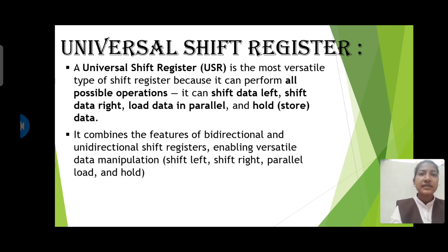Therefore, the last one is the universal shift register. A universal shift register, which is USR, is the most versatile type of shift register because it can perform all possible operations. It can shift data left, shift data right, load data in parallel and store data, which means it can shift to the left and to the right, and we can load in parallel and also store it.